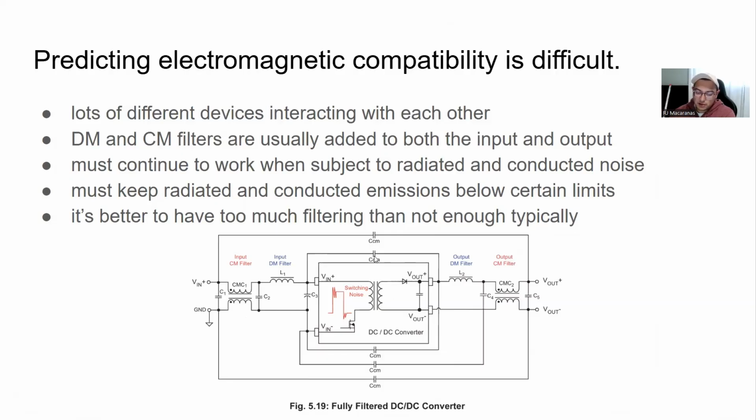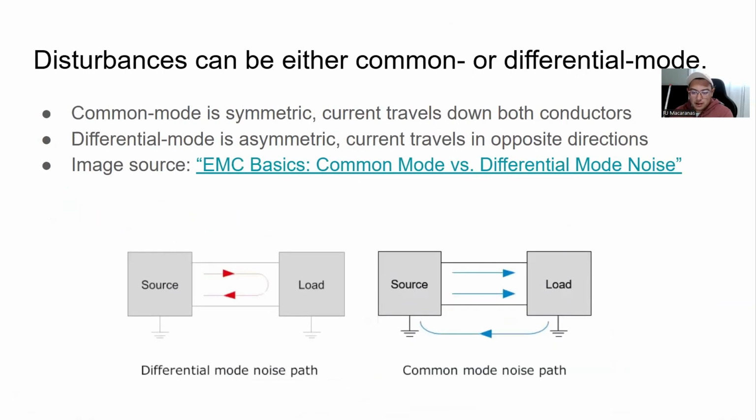Obviously we've got a switching converter here, so there is spectral energy right across the frequency spectrum. We don't want that to leak out because if it does, it can potentially cause other devices, upstream or downstream, to start breaking. We want to prevent that as much as possible. So there are often electromagnetic compatibility requirements in the form of different standards. I showed them back here somewhere.